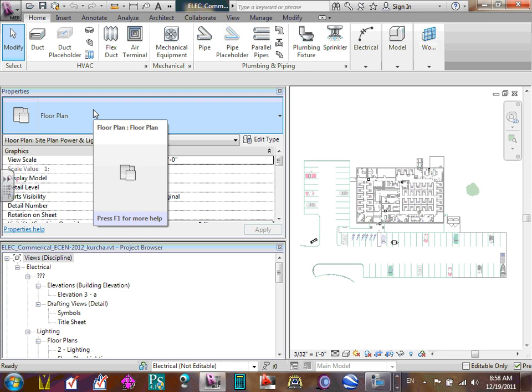So if you look at the riser I gave you guys, compared to the riser that they did last year, the project is going to be different because I modified it. We wanted just one generator to pick up the whole building. No emergency panel, no UPS panel. The only three panels we're going to have are lighting, receptacle, and main, plus an auto transfer switch, plus the generator and transformer. That's all that you're going to have.